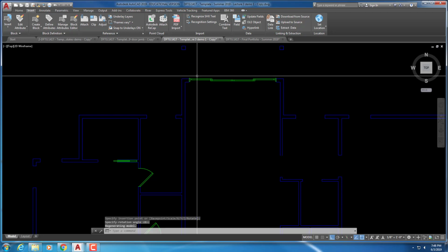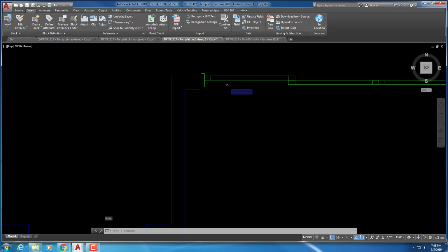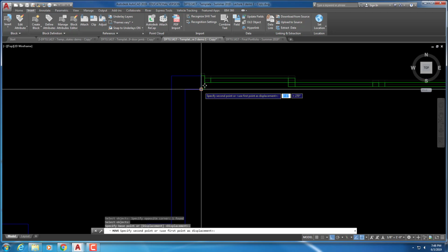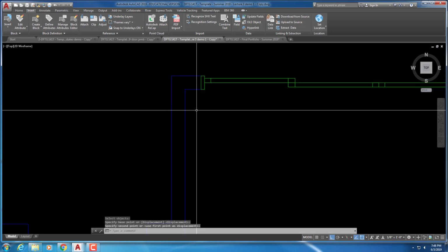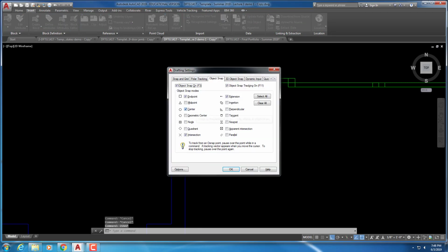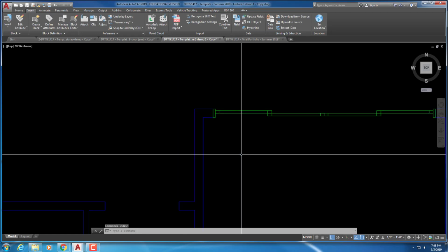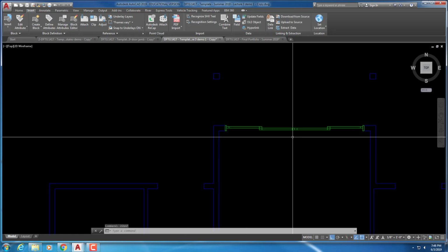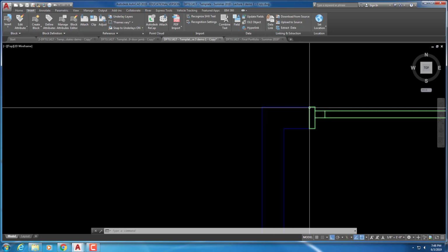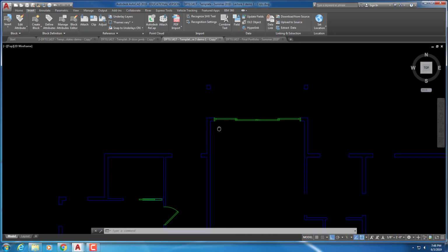The 2 doors in the middle should be to the inside, but it does need to be moved to where you align it with the wall here. Right now I have running object snaps, so that's O snap. Of endpoint, I'm going to take center off. I think midpoint's better. Endpoint, midpoint, intersection. I would take extension off and perpendicular. I think for the plan, typically endpoint, midpoint, intersection, and perpendicular are more useful. Anyway, so the doors in the middle should be to the inside, and this should be aligning the width of the wall here for that door.